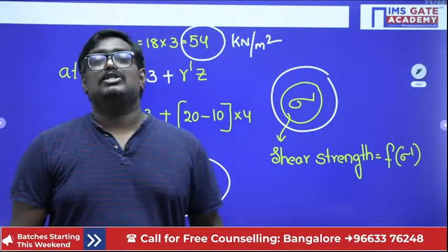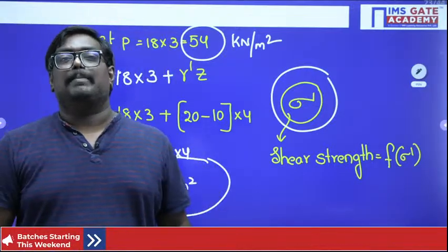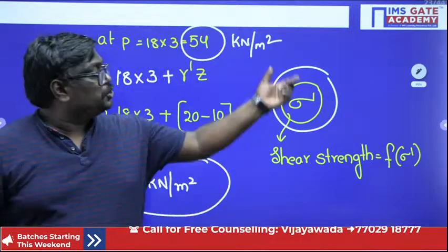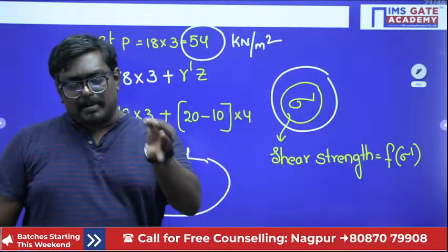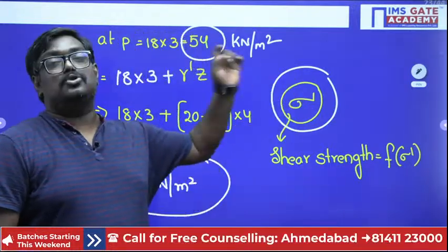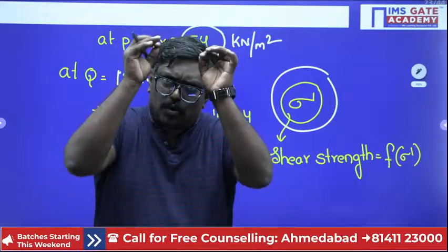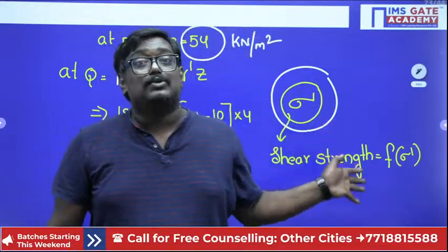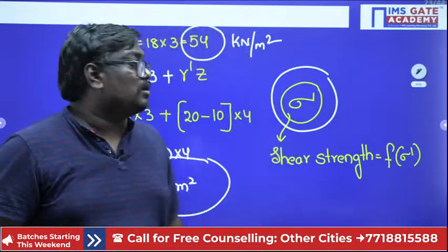That means you cannot estimate the bearing capacity. If you want to understand the settlement of a soil, you should know the effective stress. If you want to understand the stress distribution, you should know sigma dash. So if you want to understand the engineering properties of the soil, effective stress is a very, very important concept.